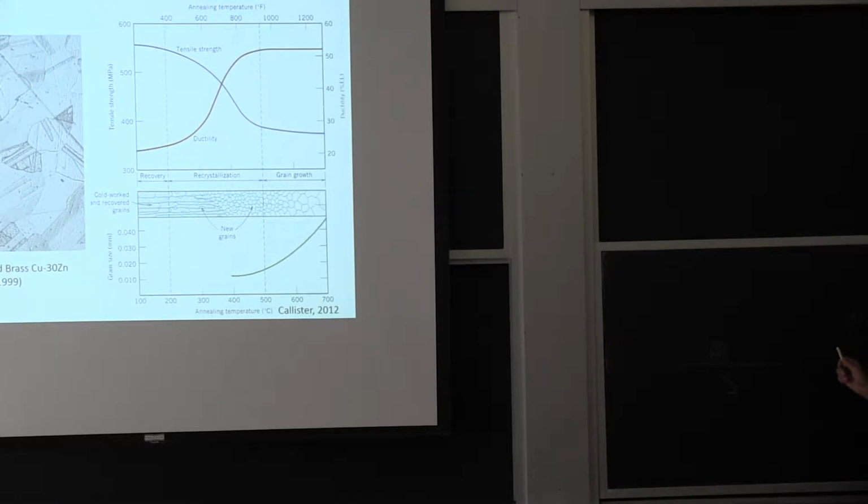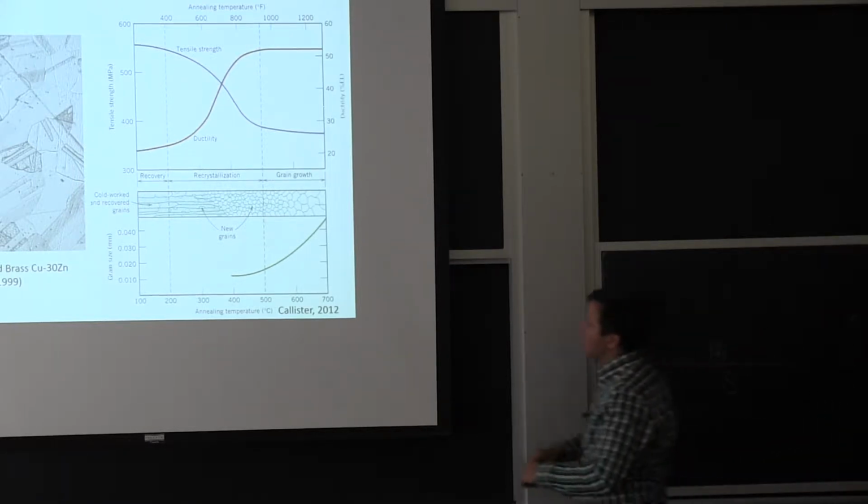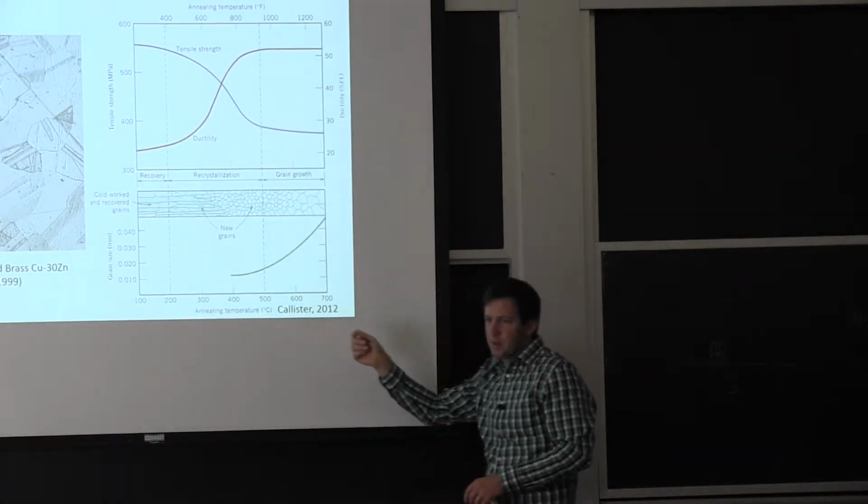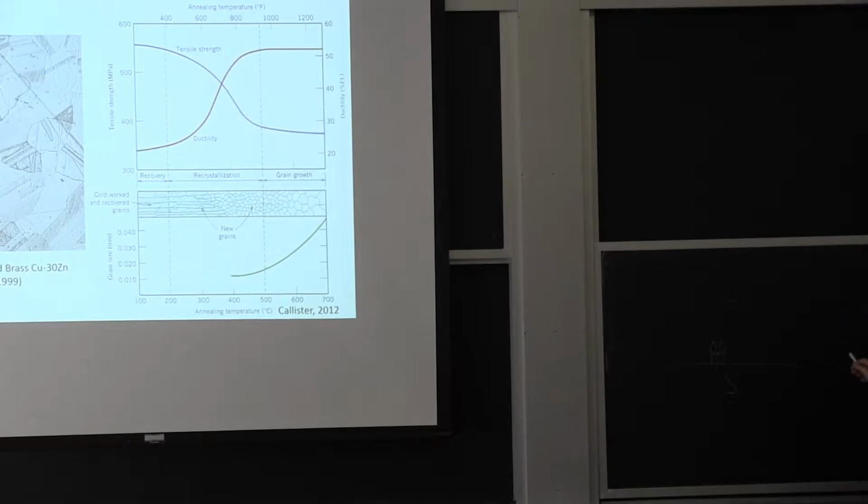Well, okay, so very, very different. The reason why we recrystallize here is because we deformed it in the first place. Over here, this structure, you get it first when you are solidifying or transforming the steel from very hot to cold temperature. Now, when you have the kind of low temperature steel and you deform it,